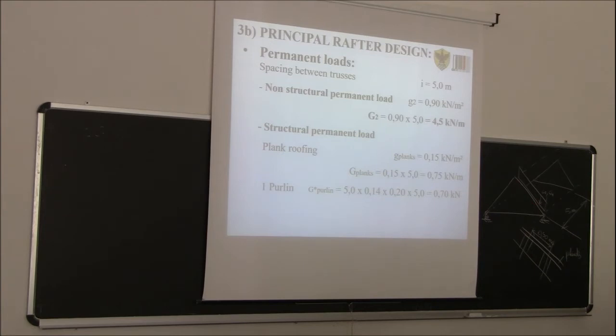Okay? Something that we saw 2 years ago. The basics of, if you remember, when we were studying the load assessment in the reinforced concrete design, we were doing it this way. Finding out the tributary width. Okay, so this is the weight of the plant. Then we need to find out the weight of these purlins. So we have, you see, some purlins every 0.5 meters.